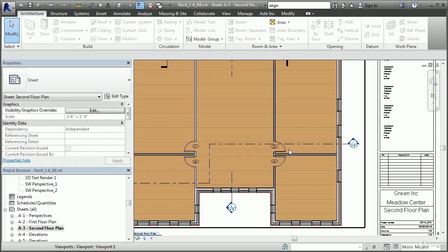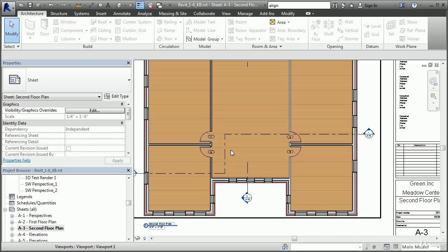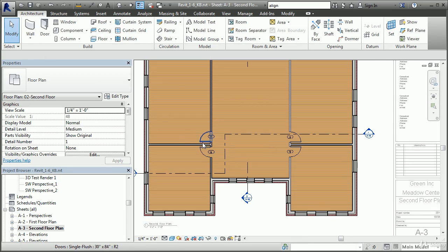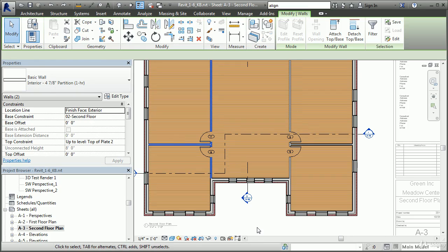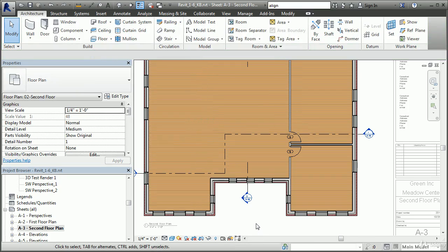Revit can create logical relationships between elements, such as connected walls or windows within a wall. If you delete a wall, it's going to delete all of the hosted elements as well. If I come into this view and I select a door and delete it, those elements are going to be removed, but the wall remains. If I undo those operations and bring them back, but I delete the walls themselves, when I delete the walls, any hosted elements are also going to be deleted. And I'll just press Ctrl Z to bring that back.